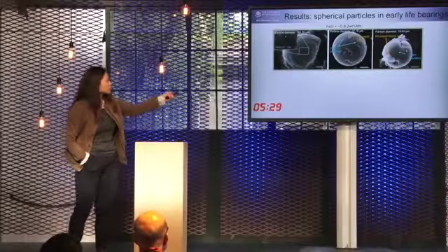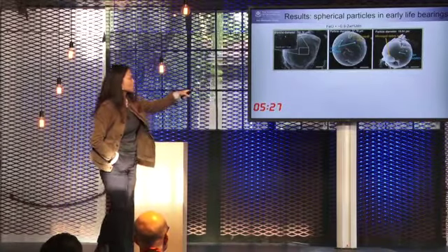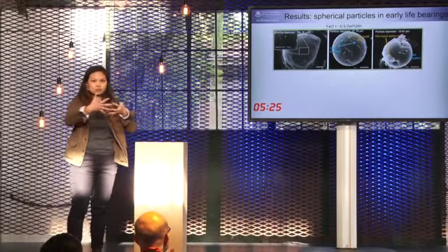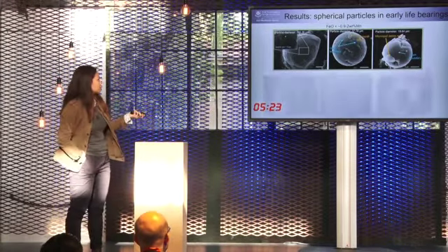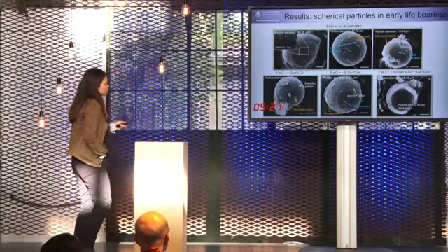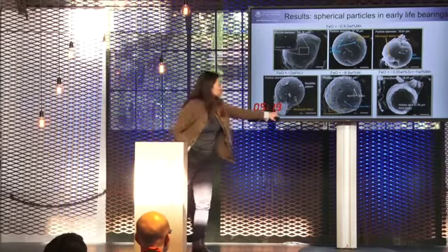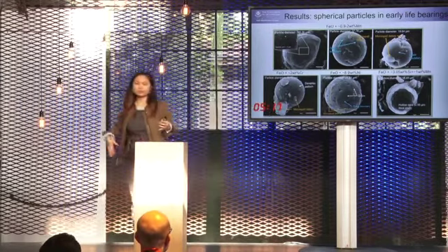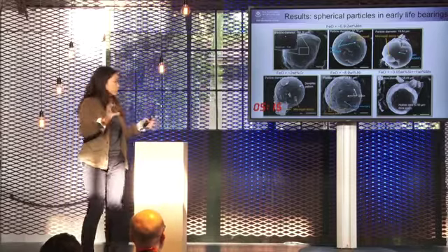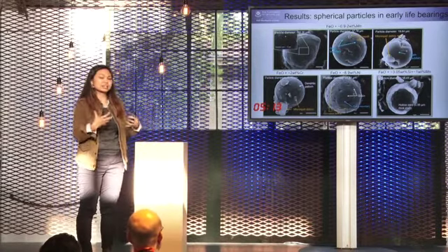This is the typical severe particle we found in the early life bearing, where they have the dendritic pattern, or a grain size pattern, or this melting stage. Also, we found microspalling particles attached to the severe particle with a dendritic pattern.